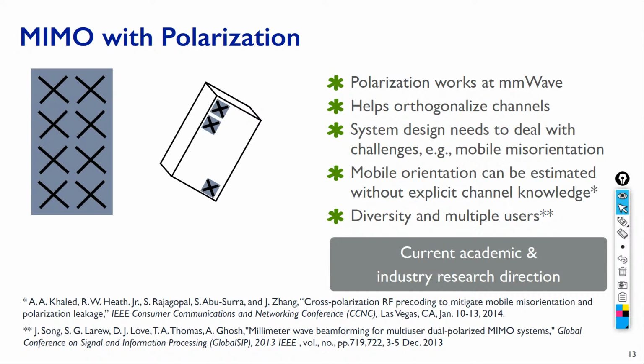Therefore, it's very recommended that you use two polarizations at the transmit antenna, one vertical, one horizontal. Why? Because if the vertical, for example, gets reflected off an object, it can change the polarization. You are assuming the transmitter and receiver have the same polarization, vertical. You transmit it vertical. The vertical hits an object, gets reflected back. The reflection changes the polarization, and now you have horizontal while the receiver has vertical.